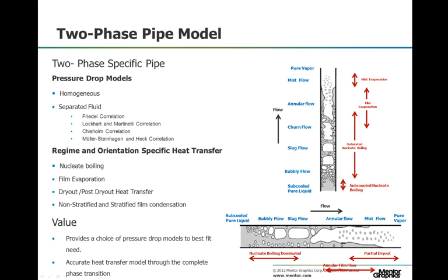For two-phase flow, there are multiple flow regimes which are also dependent on the orientation of the pipe. Additionally, each of these flow regimes have a different effect on frictional losses and heat transfer within the pipe. Flowmaster provides two different pressure drop models. First, the homogeneous approach. It assumes a pseudo-fluid condition where traditional single-phase fluid design equations are applied. To do this, fluid properties of the liquid and vapor phases are averaged. The critical assumption of a homogeneous flow model is that both phases have the same velocity and the mixture is homogeneous.